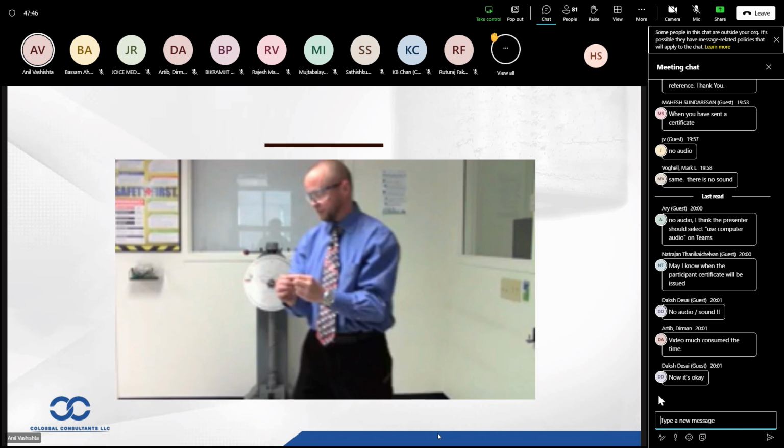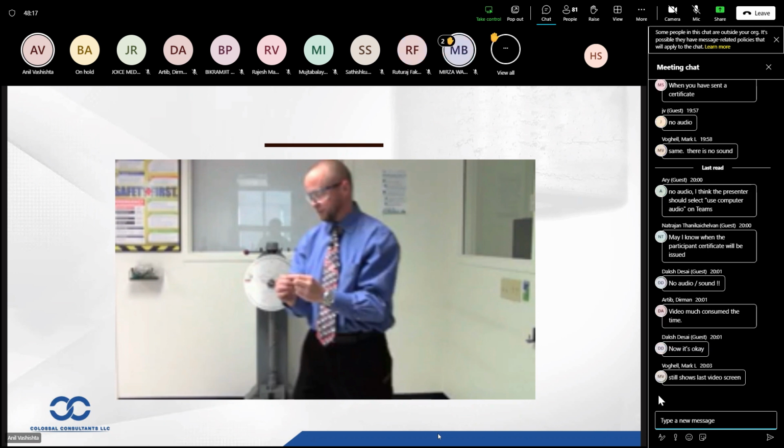EDS, most of the time associated with SEM, is used when we have deposits on the surface. Clients want to know what the deposits are, or as a part of the investigation, it will be required for you to understand what the deposits on the surface are which could have contributed to the failure. Results are semi-quantitative, and we identify the microstructural phases also as a part of the EDS. We detect the contamination, we identify the corrosive deposits.